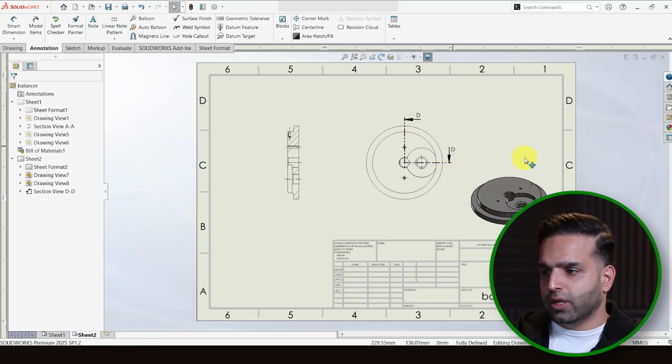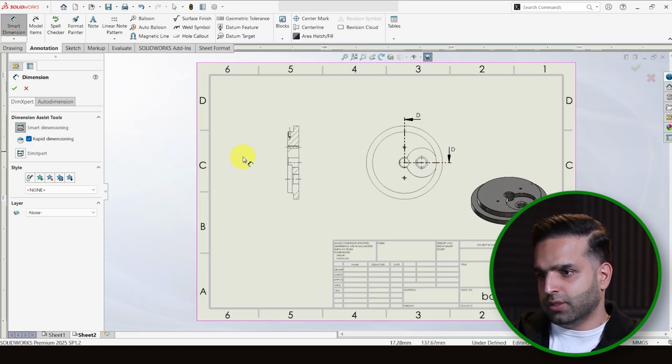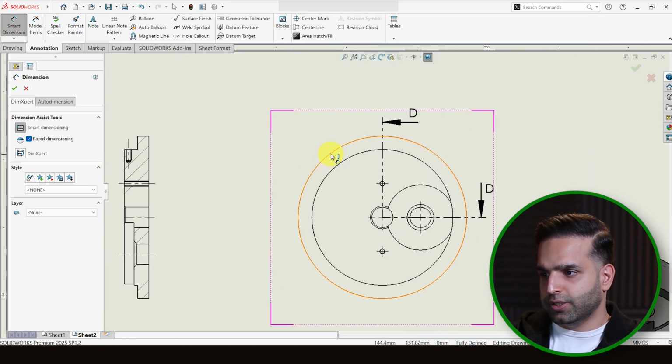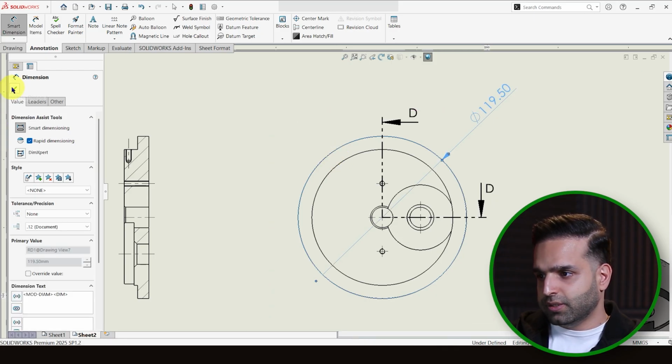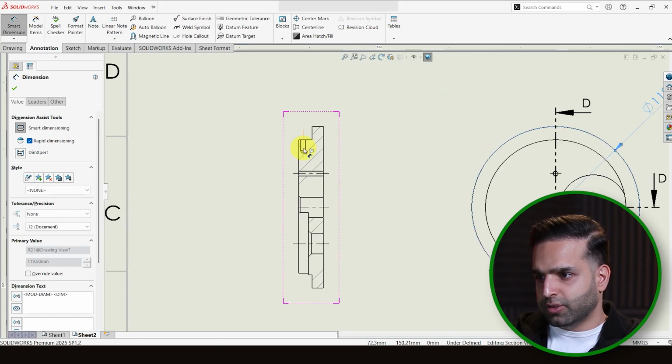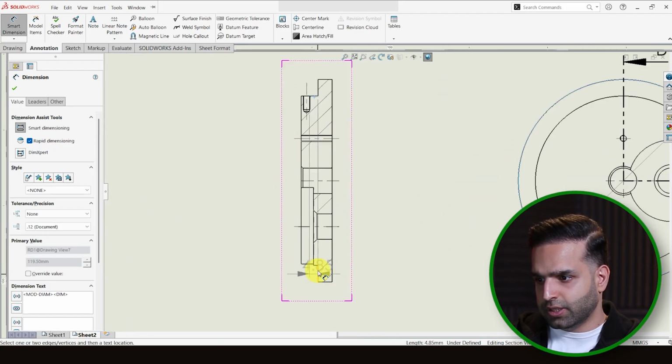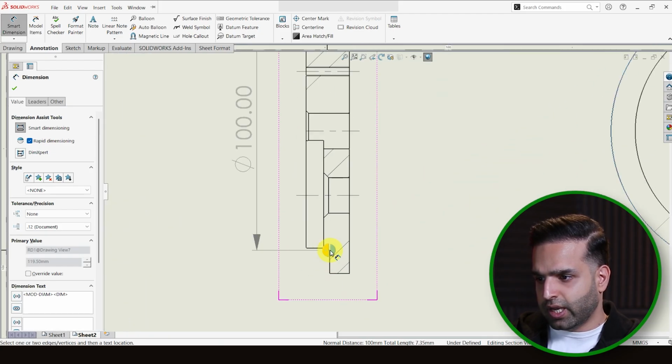Okay. I'll start by adding the outer diameter. So I grab this edge, and a small quarter circle appears that is for auto aligning. And I confirm it. And I add this diameter from here, select this edge and this one. And now we have 2 half circles. The right one, put the dimension on the right side, and the left one, put it on the left side.